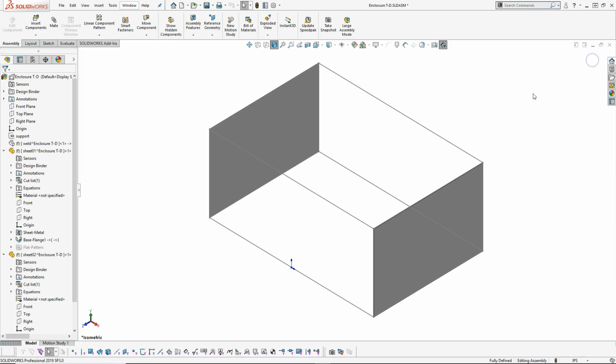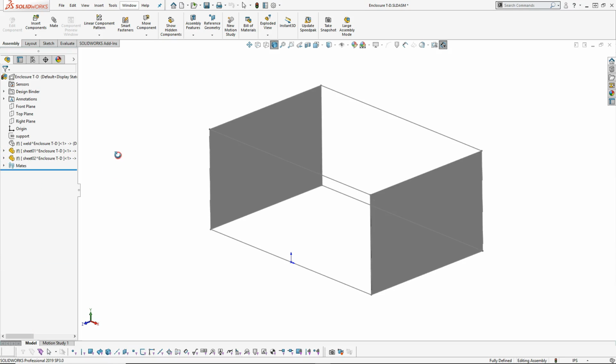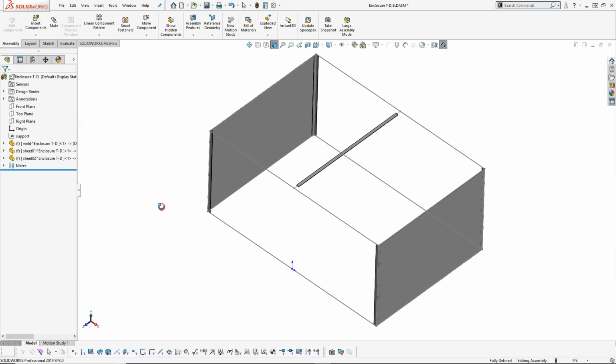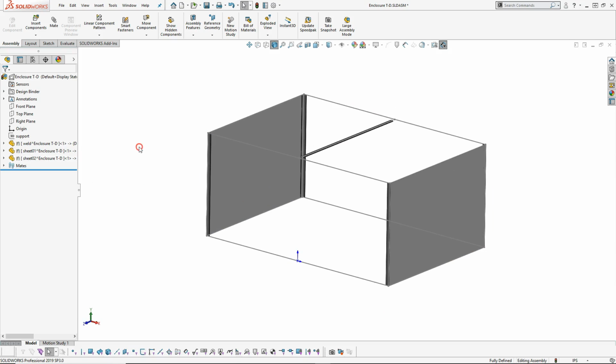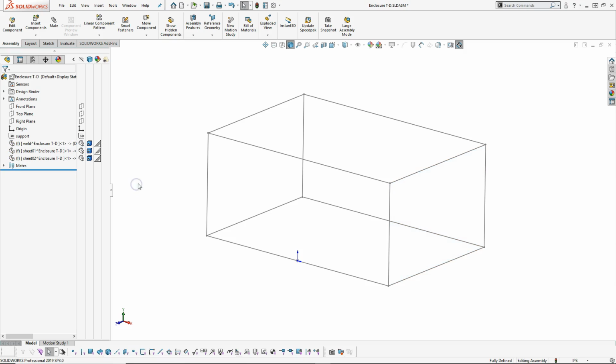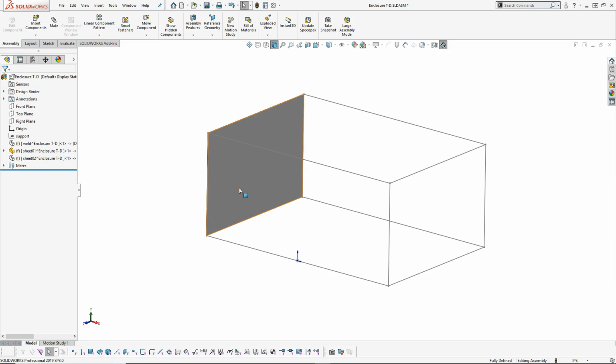Alright, so if it's kind of a jigsaw puzzle, if there are intersecting overlapping bends, this helps manage it and stay consistent with those builds. So we come back and we show the weldment, and we have some of that. So the next would be some top piece, and we could pick a slightly different naming structure if we needed it. Alright, so if I expand out and hide all of those, because this is the assembly, I could also hover and hit the tab and shift tab to bring them back. So shift tab, tab to show.